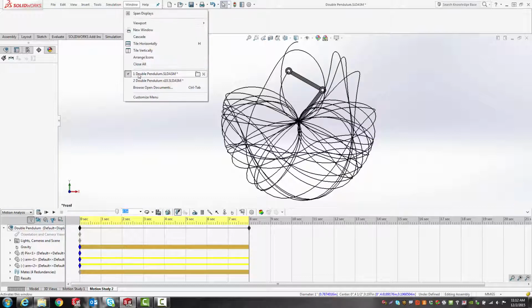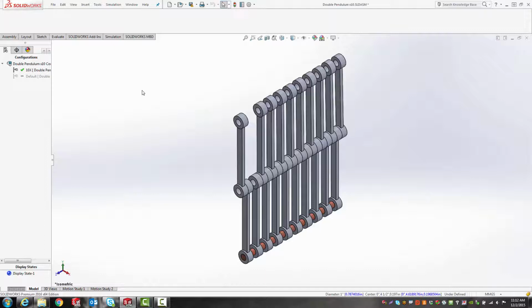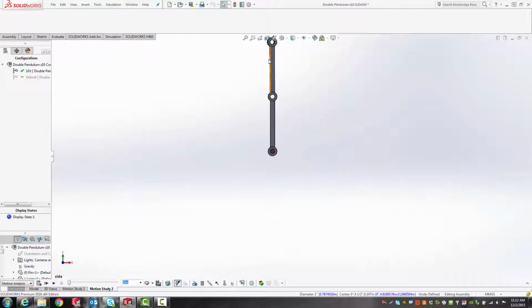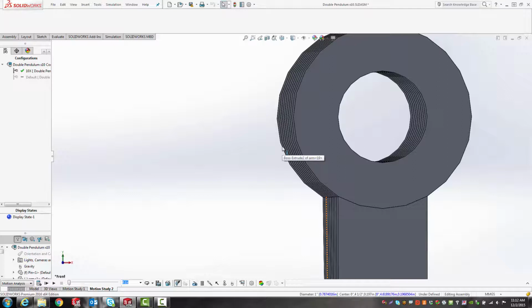Another way to look at this in SOLIDWORKS, since all the materials are free, would be to create a larger assembly with more than one pendulum, all starting from a slightly different position. Here I've got 10 of them, all on the same axis, and I've got their starting positions offset from each other by 1/10 of a degree.